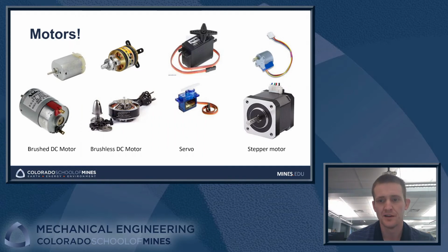All right, first of all, let's lead off talking about some different types of motors. In your kit, you'll actually find several of these types. The first one is the brush DC motor. This is a common, inexpensive type of motor that uses a permanent magnet inside of it to help generate a magnetic field that keeps the motor spinning. Next up, there's a brushless DC motor, which is found in fancier power tools and also things like drones and RC aircraft. Generally, a brushless DC motor for the same power will be lighter weight, which is why they're popular for those drone and power tool applications.